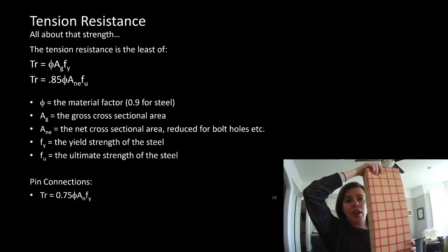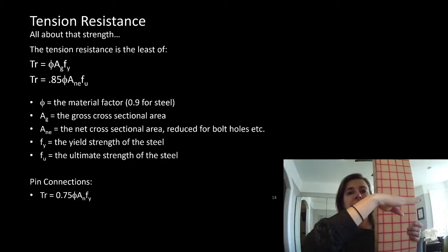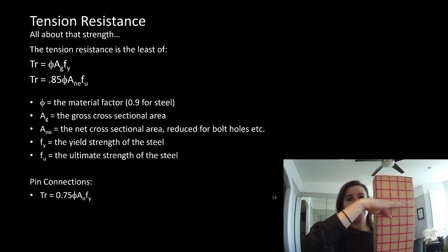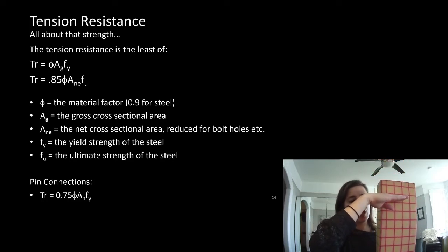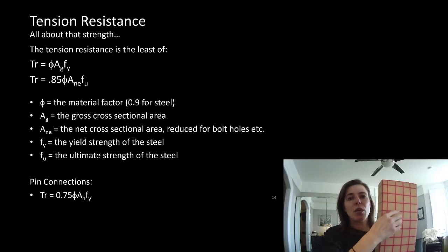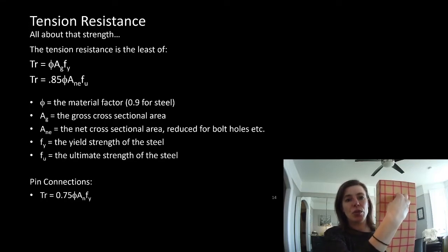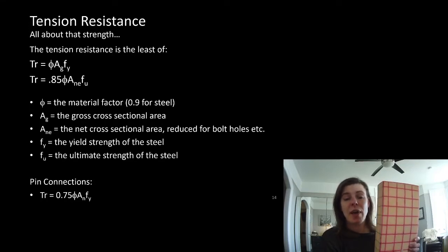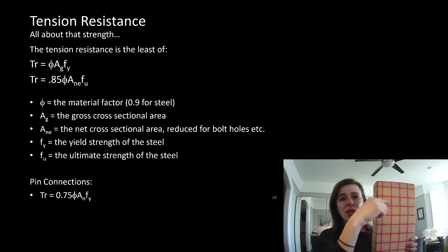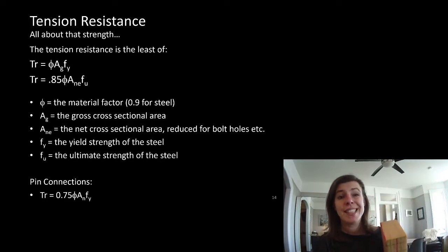I've got my tension on it, and the tension here is the same as the tension here, which is the same as the tension here, which is right through where the circle goes through, or the bolt hole that's in my element. The cross-sectional area there is different. It's less. We've got less cross-sectional area. So, do we use that area?